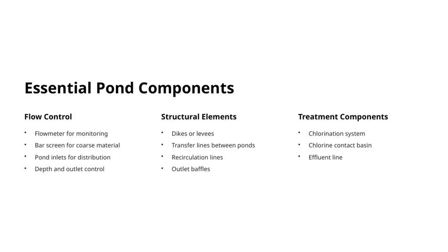Transfer lines connect different ponds, allowing water to flow seamlessly from one stage to the next. Recirculation lines help optimize treatment by reusing water within the system, and outlet baffles are installed to control the flow exiting the pond, ensuring proper mixing and contact time.